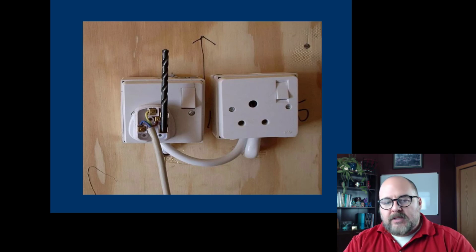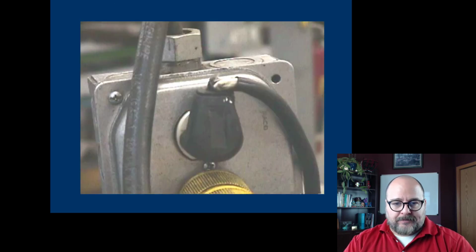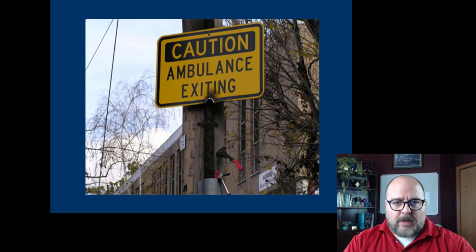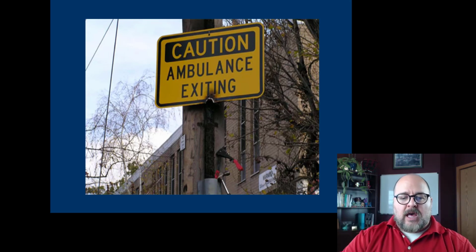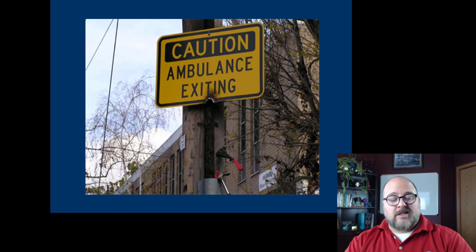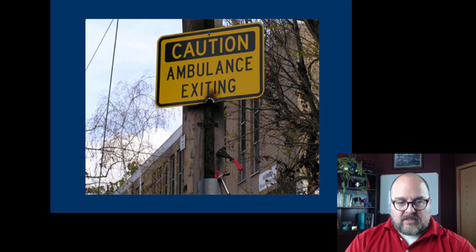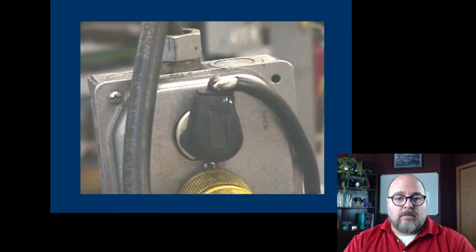Somebody used a drill bit as a fuse. Can't do that. Well, it looks like a line was fried. You can see that there was an arc here, an arc event. It melted part of the sign, and you can see how it's all fried. What happened? I wonder if the sign, maybe because of wind, pierced the cord, and that's probably what it was. I bet that's what it was. So you can't be hanging metal signs near a conduit like this. It pierced it. That must have been it. The wind must have moved it.